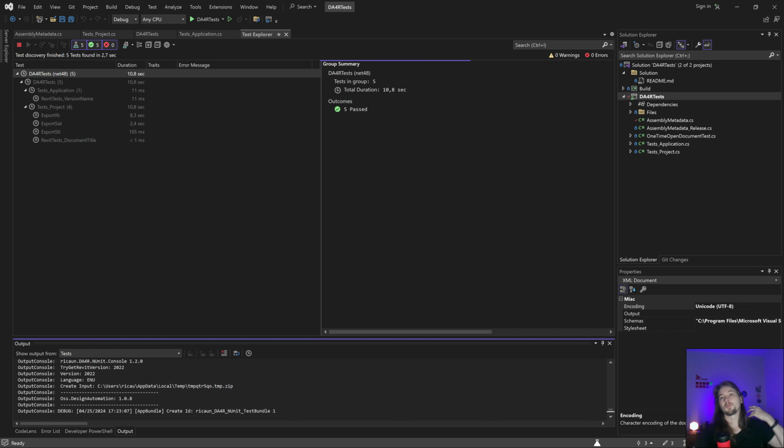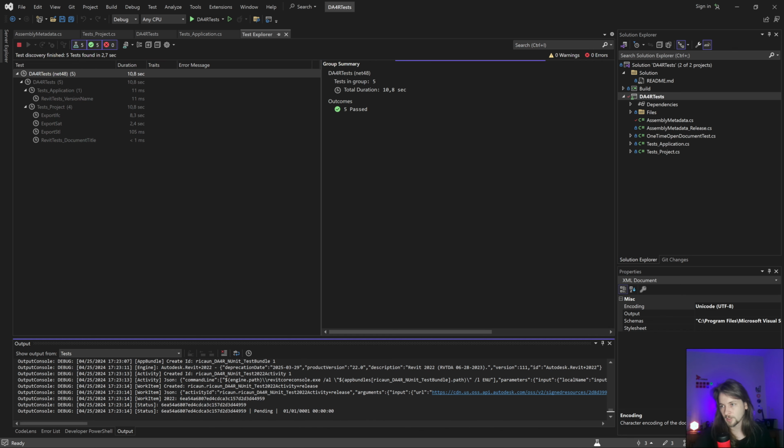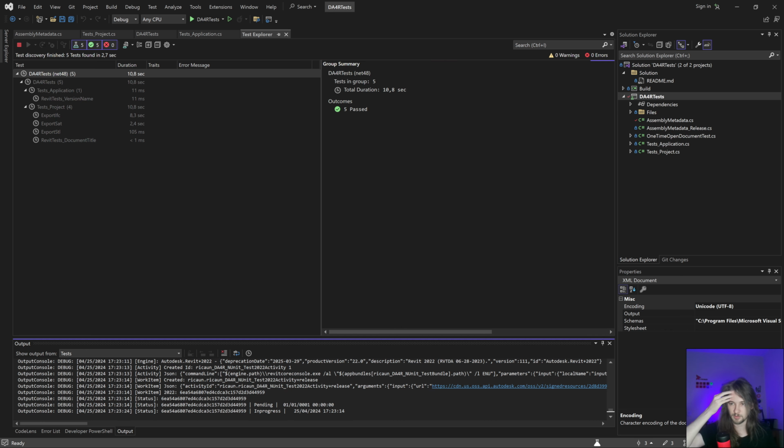I'm gonna do all the same thing, and use the engine 22 for Revit Design Automation, and run the test in that. Let's wait. It's pending at the moment, but it should take around 30 seconds. That's usually what that does. That's a little slow to export to IFC, but yeah,